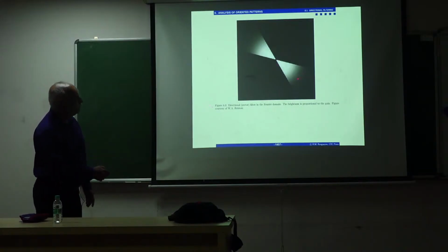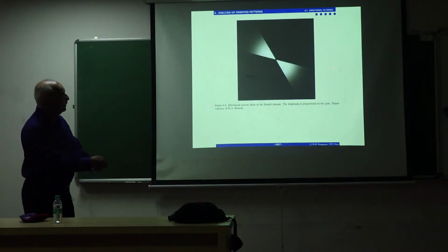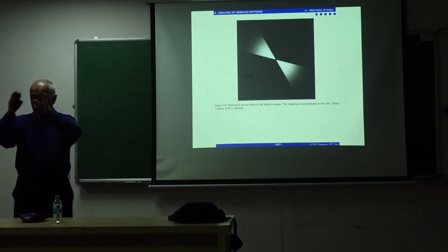The gain reduces as we go to higher frequencies. The gain reduces as you go away in angle from the center of this angle band, and the gain also reduces as you come towards DC. There is a high pass filter. There are 2 low pass filters, the ramp and the Butterworth, and the cosine weighting makes it smooth.